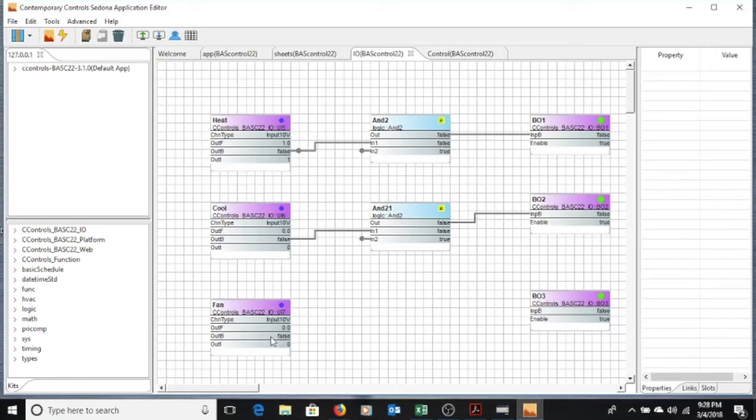So you do not have to worry about that. Output binary. When that fan switch goes, it turns and pulses 24 volts to the green, right, on your actual furnace terminal board. So what we have here is we got our control, we got our I/O.